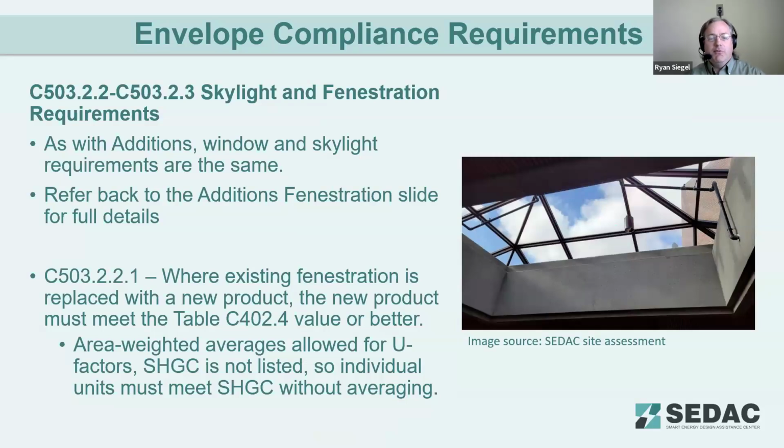Skylights, again, fairly similar to the fenestration. You cannot increase the size beyond the limits, but if your envelope already is above the limit, you may maintain that for the alteration that you are doing.